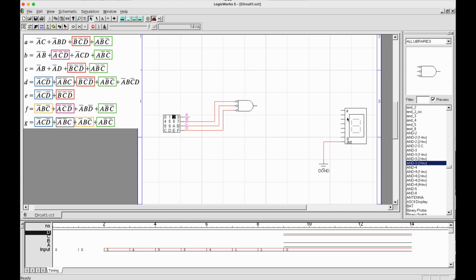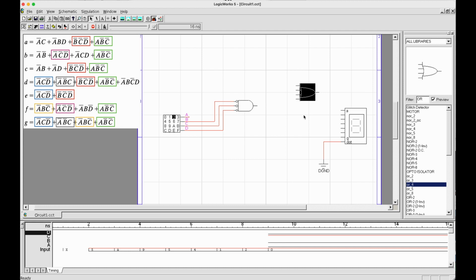What we also need to figure out is a series of receiving ends on the output side. So let's take a look at A. A is going to need 4 different OR terms connected together. So let's get some ORs. This is a 4-input OR gate. We can simply use it here. This is for A. B is also going to need a 4-input OR gate, so this is B. Let's connect them briefly.